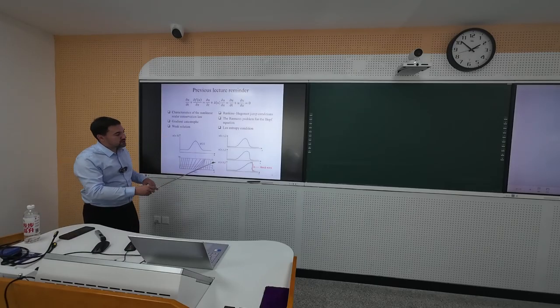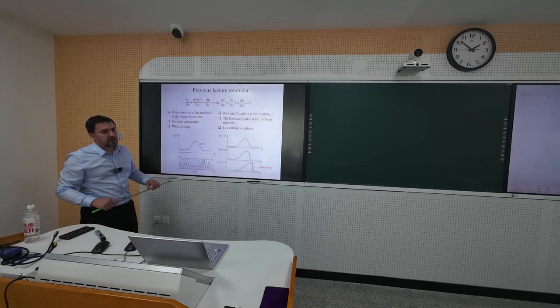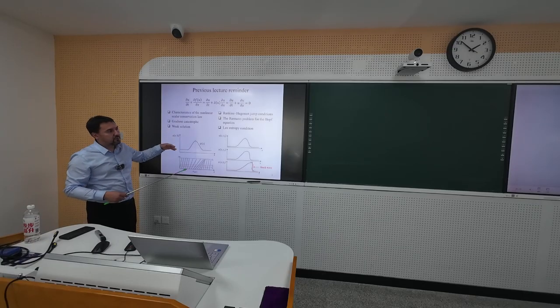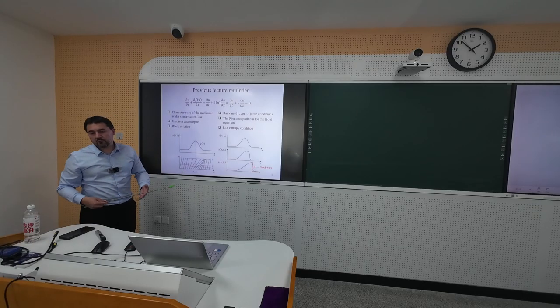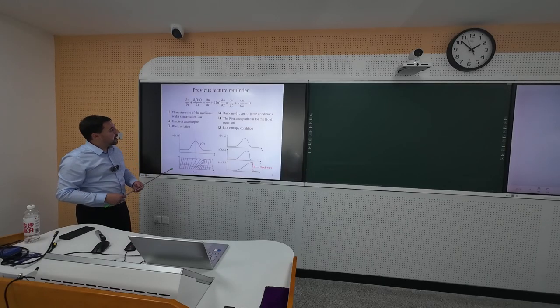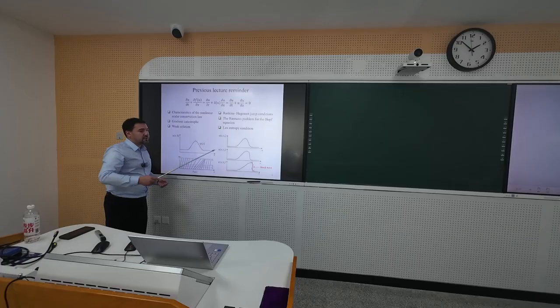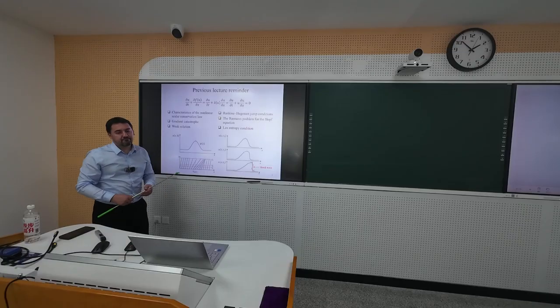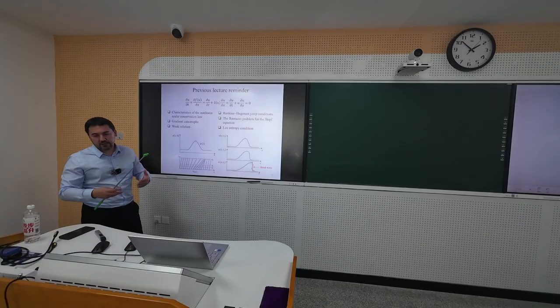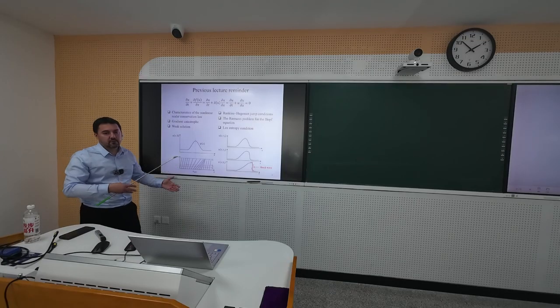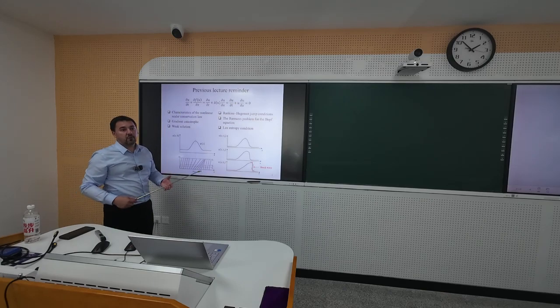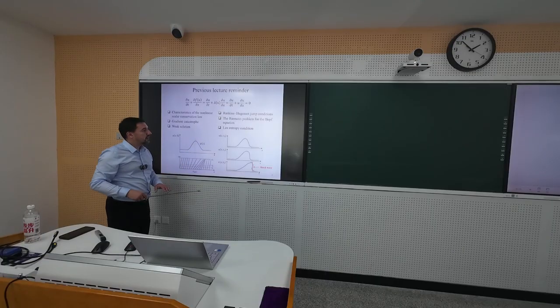But if we want to consider shock waves or discontinuous solutions, we should introduce so-called weak solutions. Weak solutions are solutions that fulfill not the differential but the integral form of the equation. And we discussed the Rankine-Hugoniot jump conditions. The parameters to the left and to the right of a discontinuity cannot be arbitrary. There should exist a relationship between the parameters in front of and behind the discontinuity and the speed of this shock wave. We derived these jump conditions for the Hopf equation.